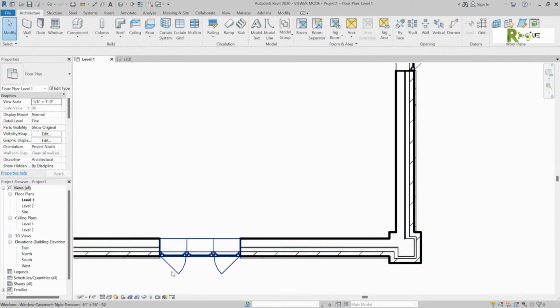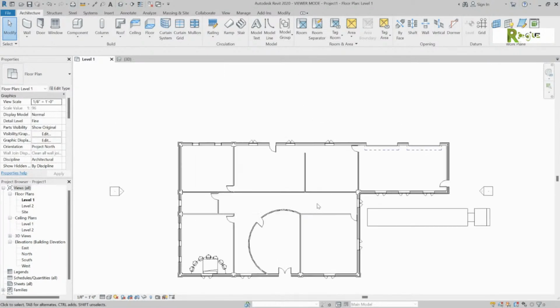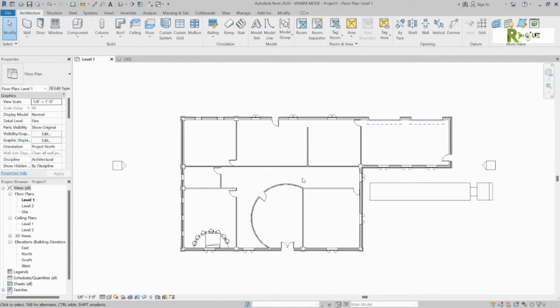So that architectural column is a very special object, okay? Because it inherits those materials. A regular family and a door and a window, those kinds of families can't do what that architectural column can do. How does it decide the low wall versus the high wall material? It's the order and the components setup of that actual wall. And remember, that wall's a little bit of a crazy wall, to be honest with you.